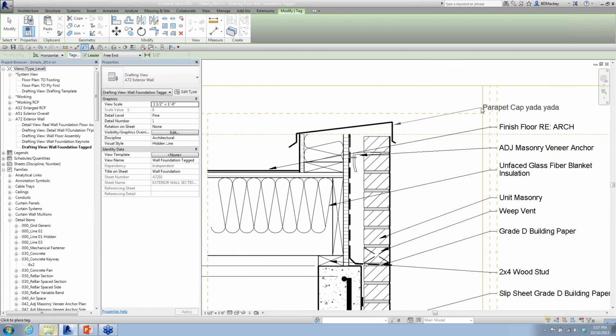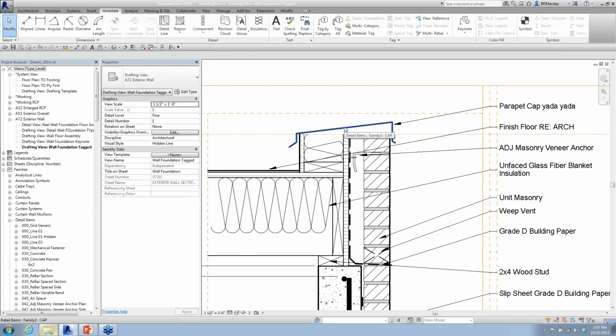So even if I'm on a project that has a single family that doesn't need to be parametric, it's specific to this project, I just simply draw it in the project because that's where the lines are going to be easy to do, cut it to the clipboard, paste it in a family, load it in, tag it, there we go.